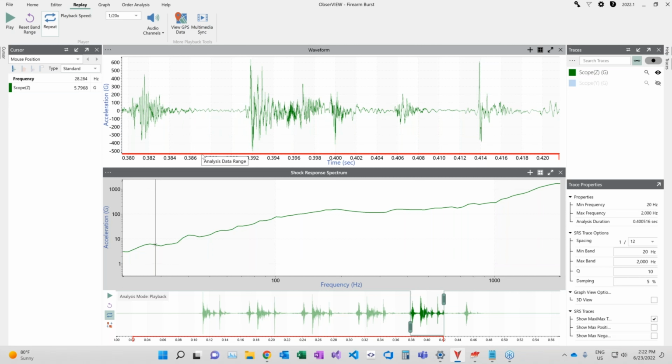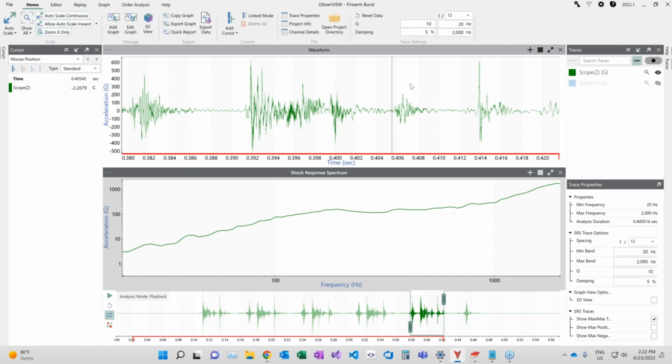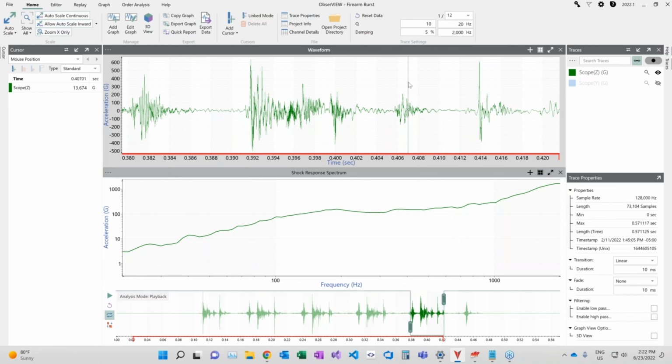But it is, again, a pretty helpful diagnostic tool, so you could listen into specific frequency ranges. For instance, I could listen into just the engine RPM frequency, or I could turn off the engine RPM frequency and try to listen to the road noise from the suspension. So that's audio playback.